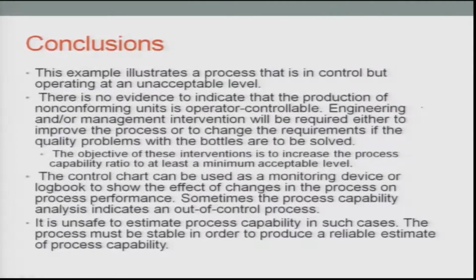The control charts can be used as a monitoring device or logbook to show the effect of changes in the process on process performance. Sometimes the process capability analysis indicates an out of control process, and the last point mentioned here in the slide is that it is unsafe to estimate the process capability in such a case. The process must be stable in order to produce a reliable estimate of the process capability